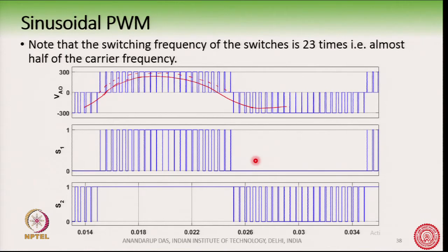This again will require heat sinks of different types for S1 and S2, and subsequently also for S3 and S4, which is kind of challenging, right. So, for this operating condition, the outer switch S1 will have more losses as compared to the inner switch.